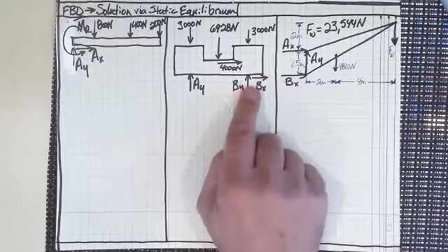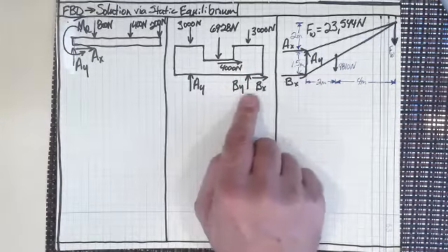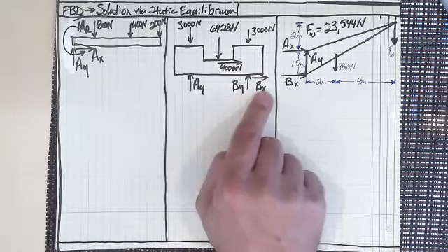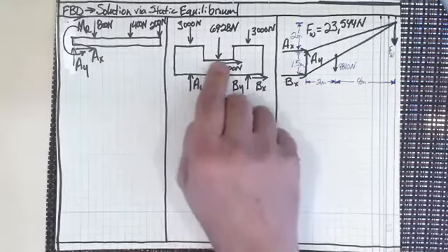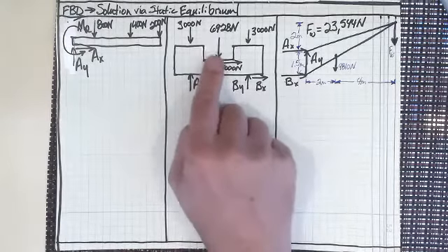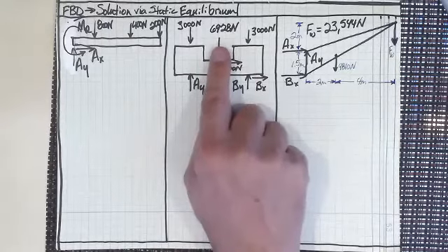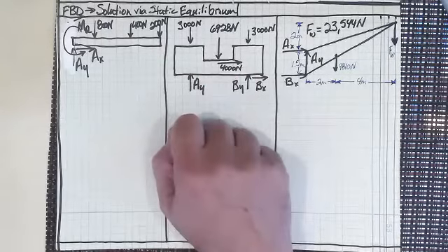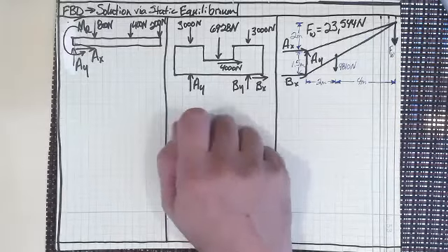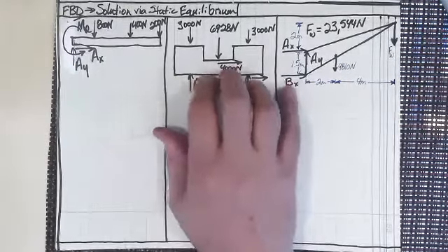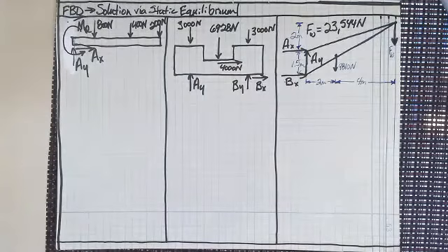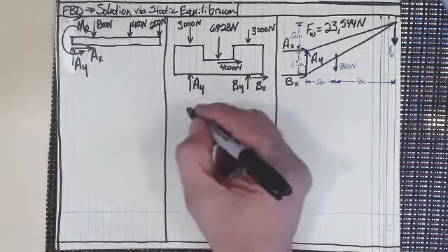This was a hinge pin, so it stopped forces in the Y and the X direction, right? And I've broken down that force in the middle here into its 2 components, 6928 in the Y or vertical direction and 4000 in the X, and we've already partially solved this problem, right? So that's what I want to do. I want to start with where we left off in the last lecture.